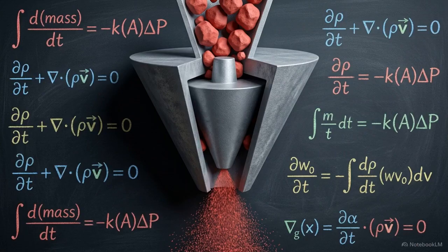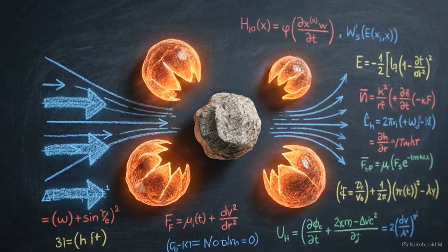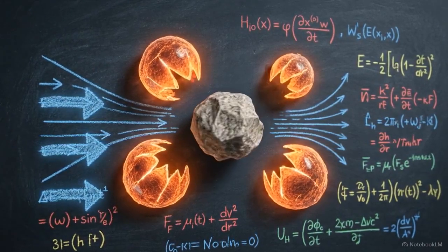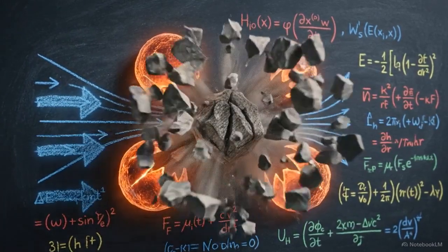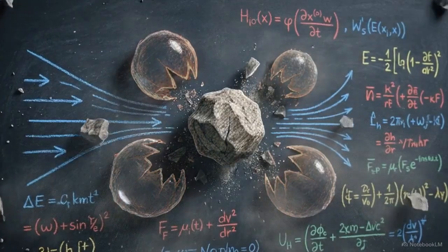Top-down dispersion relies entirely on applied mechanical force. Colloid mills grind coarse material using extreme shear forces between static and rotating cones. Ultrasonic treatment passes high-frequency waves through a medium, generating alternating regions of compression and cavitation. The violently collapsing cavities shatter coarse particles on impact.